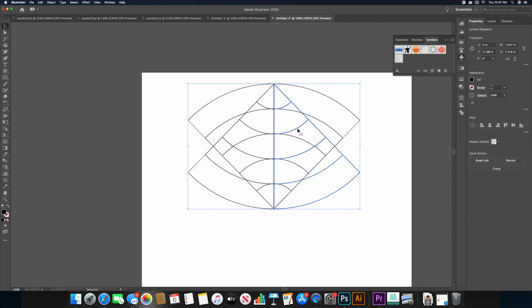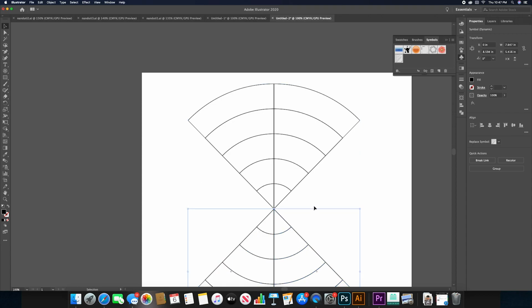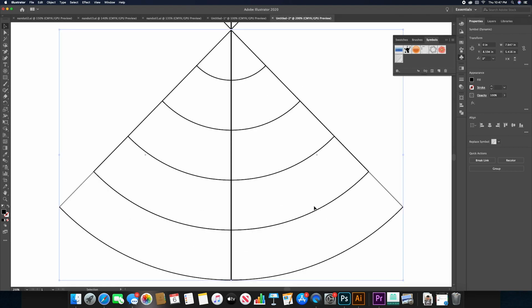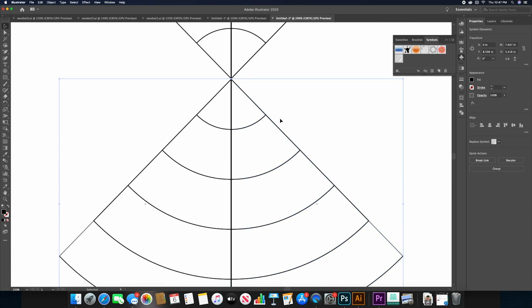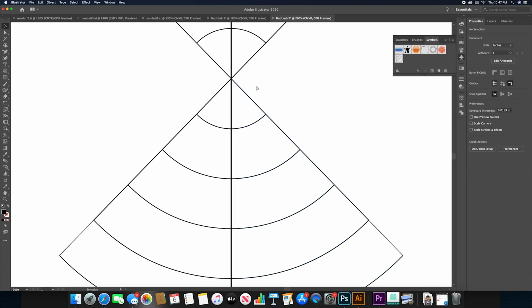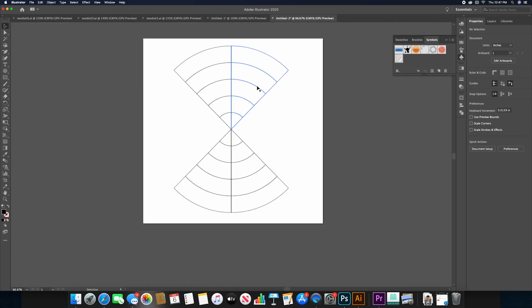To slide this down, I'm going to again grab from one of the black lines of the two objects. I'm going to click and drag downward, and as I drag down, I can hold Shift to maintain alignment. And I want to get that intersect, meeting in the middle. But again, if you have any additional little areas, you may need to nudge the object slightly up. So I can use my arrow keys, just tap it up once, and now I have everything aligned.